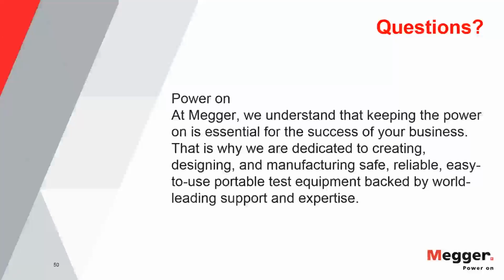Now there's of course online and substation-specific PD monitoring. So it's a big difference between offline diagnostics and PD monitoring. Megger has a few of these tools as well. This is mainly done by UHF and radio frequency measurement with devices that can be called handheld. They're not very, very large.